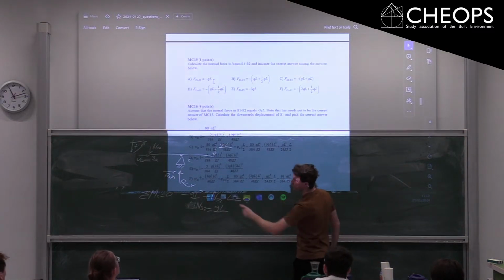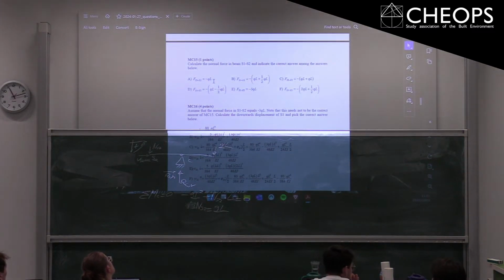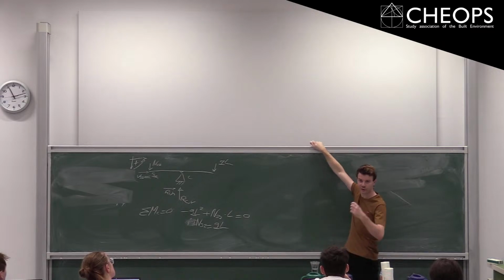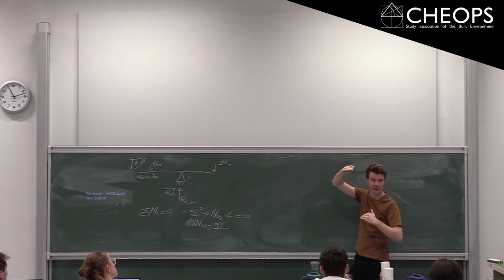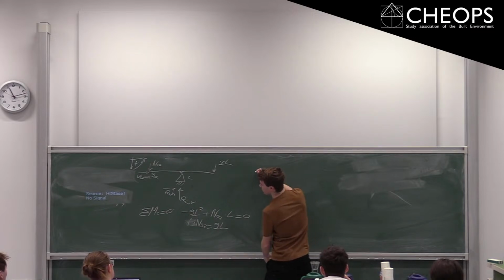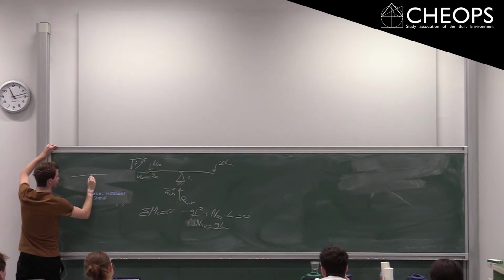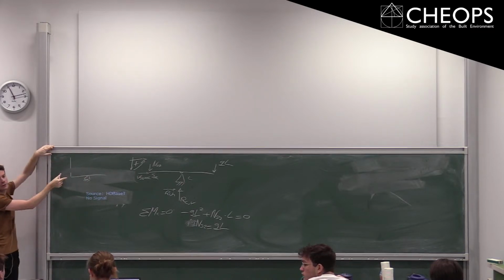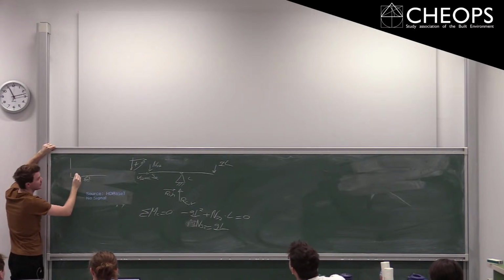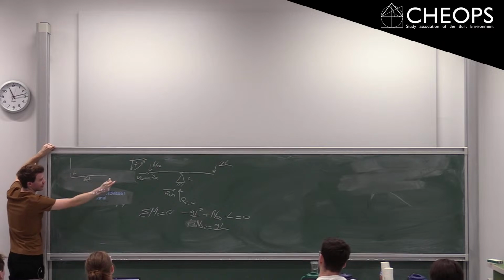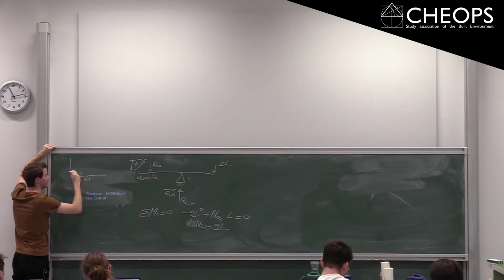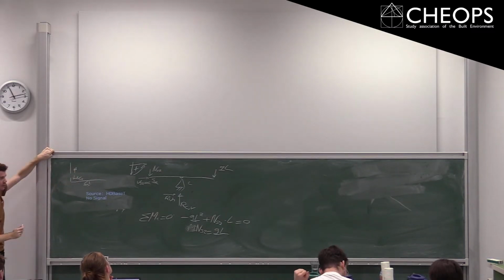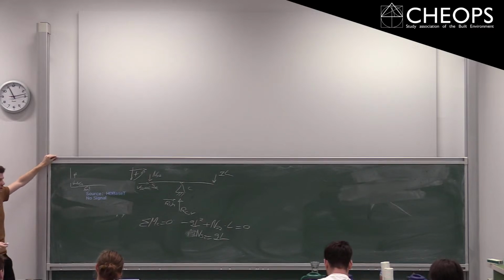We made a cut over there, right? So let's turn this off once more. We made a cut here. As you know from statics of structures, if you make a cut, the two forces on either side must be in equilibrium, right? So if I draw it, well, slightly larger over here, you had your point C, and it goes here at the top. We made a cut basically here, and this part is infinitely small, like negligible. That means that we assumed a force in this direction, NS2, but that means that in that member, it's actually in compression, right? This is that same force, but mirrored. So your S1, S2 member will be in compression.